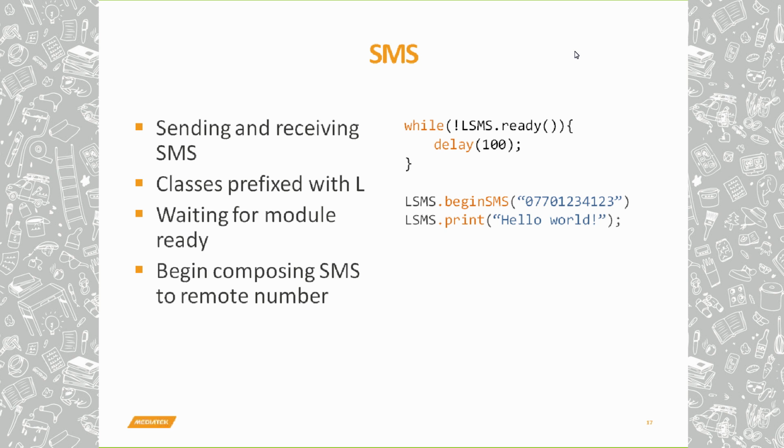And then we use LSMS.print to specify the message we want to send out. And to finish it off and send it, it's LSMS.endSMS. This again will give us back true or false, depending on whether the SMS was sent successfully. So as you can see, in about 4 lines of code, you can send text messages. It's very easy to use without any AT commands or configuring anything.